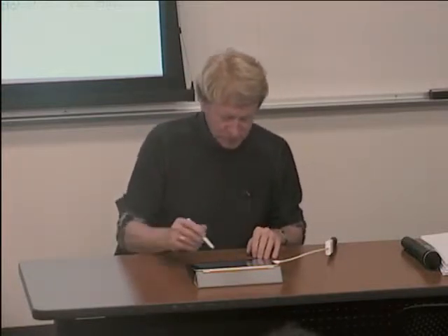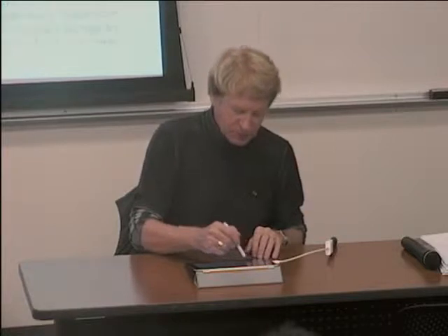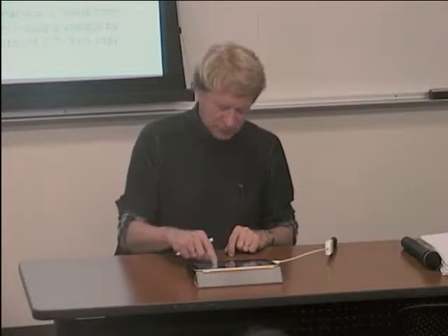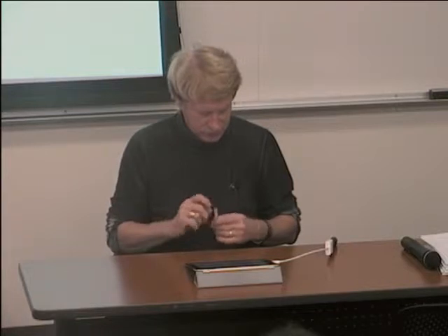You fill it in, you divide it out, and you get basically the cost per chip is 9.28. There's new NRE with this now because we had to redesign it and we had to make new masks, which were more expensive. So I get basically $0.25 per chip as NRE cost. And total is 9.5. Okay? So that was kind of the gist. Most of you did fairly well on this question. Some little deviations here and there, but the average on this question was quite good.